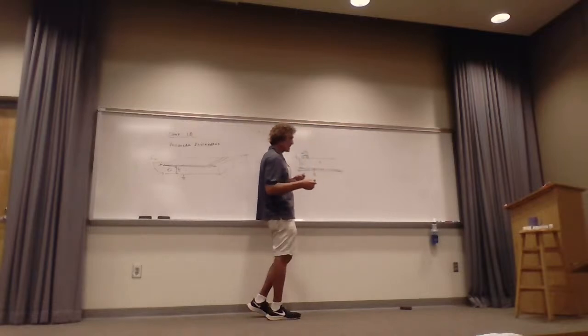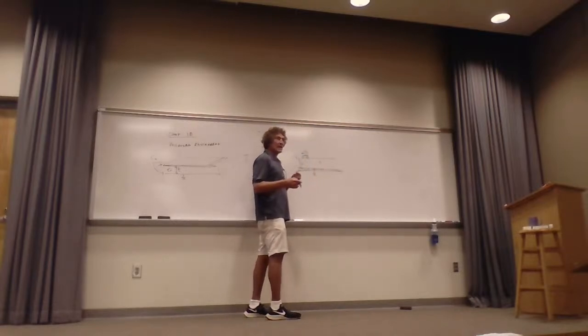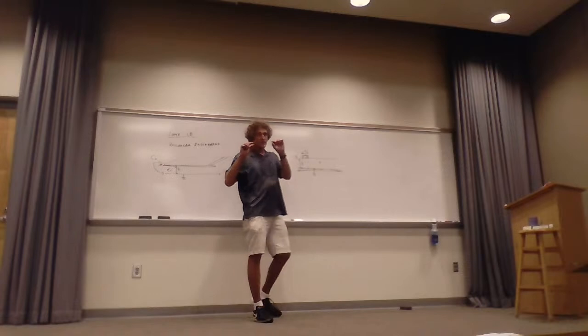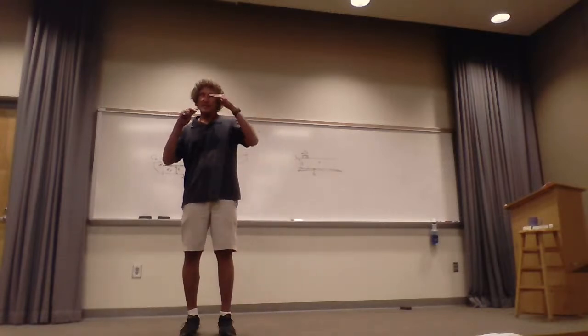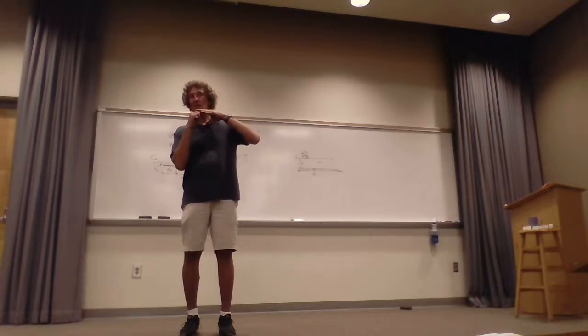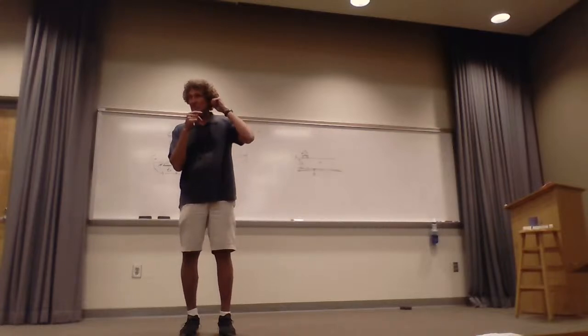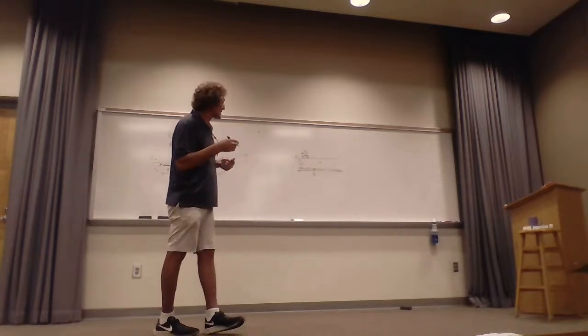And if I can, I'll bring a board in. I used to get them from Joe Haggerty. He's retired. But I'll show you what these things look like. They're very thin. They've got copper on one side, copper on the back, and then they've got a dielectric material. Now that dielectric material is a very low loss material, so they can send signals and don't have to worry about a lot of dissipation in the board material.